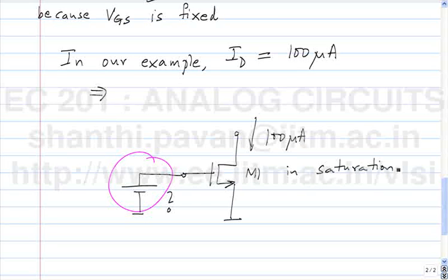She says you put in two values of VGS, you measure ID, then you can go work the math, right? You find Vt and you will find mu and Cox. You need two equations, since you have mu and Cox and Vt to find. Okay? You put in two different values of VGS, measure the drain current, figure out Vt and mu and Cox, and boom, you can get the VGS1 required so that the drain current is 100 microamperes.